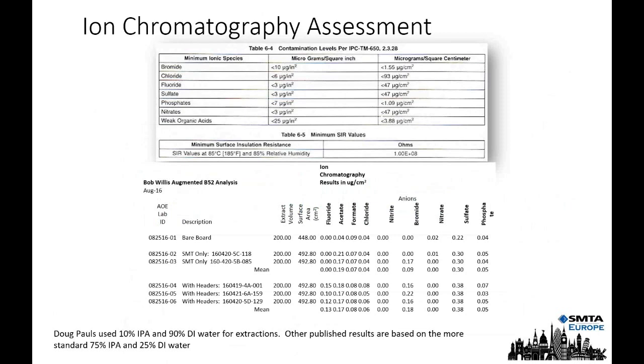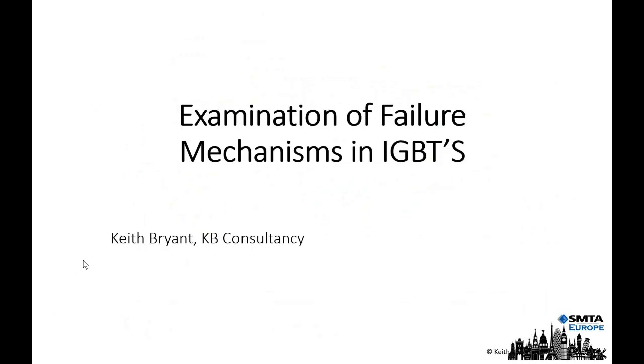He also tested some of the boards for contamination using DI fluid, so isopropyl alcohol and DI water, and did chromatography testing, and these are some of the results that we've got. And I put the criteria in, so when you get a copy of the slides, you can relate the criteria in the IPC standards to the results that we've got. I'm not saying these are perfect, but they show you the whole of the process that we've gone through on this type of evaluation.